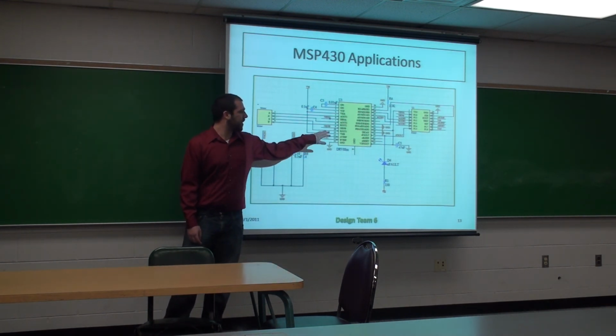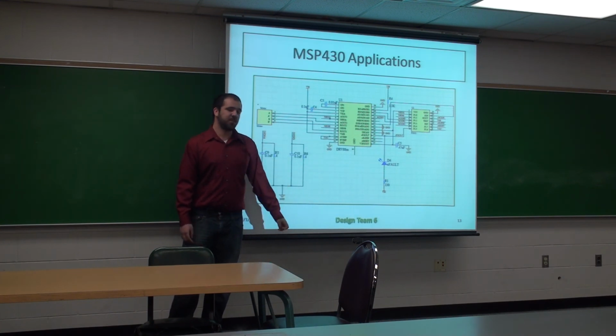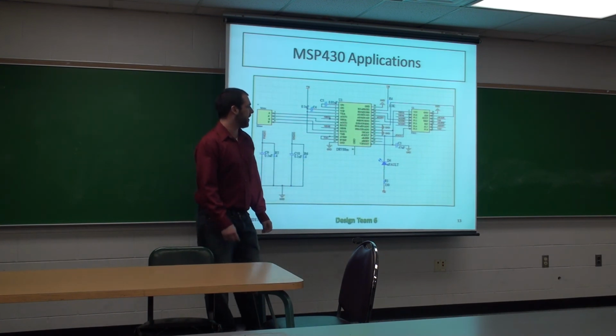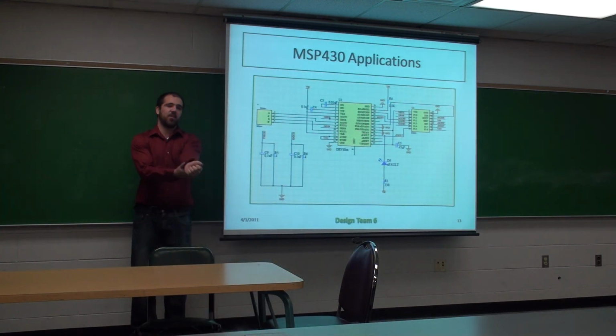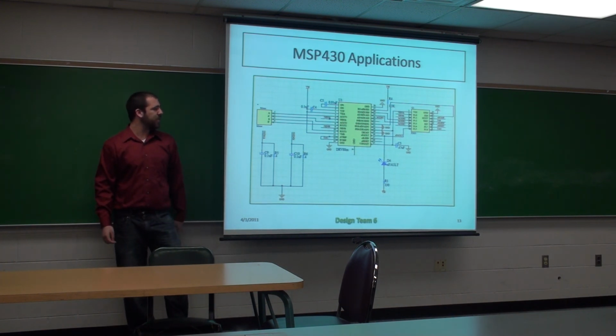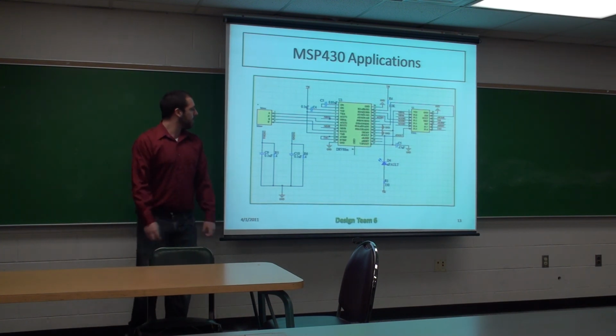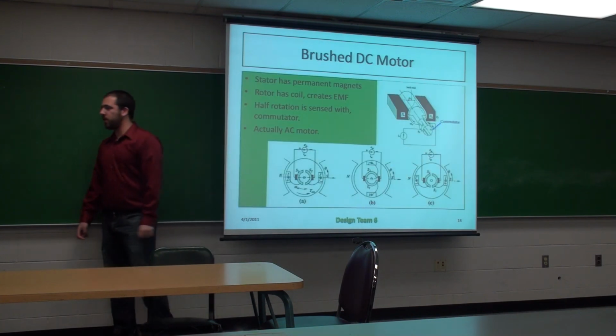Real simple. All these right here, except for the DAC, are just straight up inputs, so they're really, really easy to implement with any microcontroller. And nHOME is a really nice feature also, because with nHOME, every time you make one complete rotation, it goes high for a pulse. So you're able to calculate your RPMs if you want. And next we'll be passing it off to Pat.